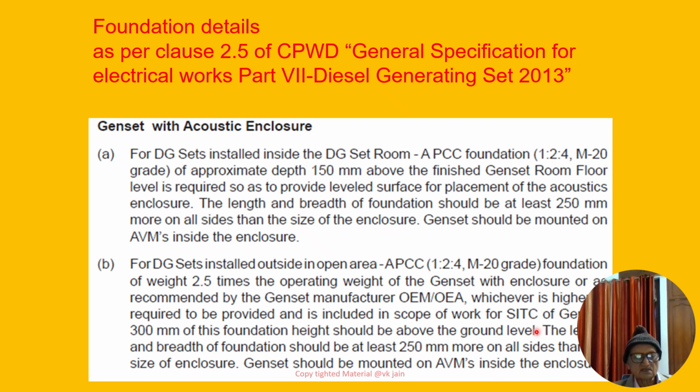The length and breadth of the foundation should be at least 250 millimeter more on all sides than the size of the enclosure.